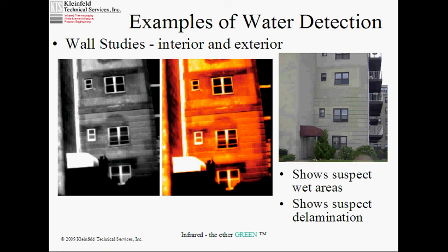And what you end up seeing is the dark areas that are not ascribable to visible impact. In other words, you can see this building's been patched a fair bit. And it's not a new building, this is a 1920s era building. It's stucco over terracotta, and it helps to know what your construction is. But there's nothing visible corresponding to this cool area. Probable water. There is some correspondence, so this is probably just a difference in the patch, although the patch doesn't quite run contiguous the way this does. So you got a possible problem here.